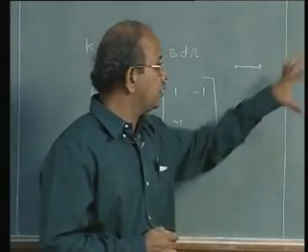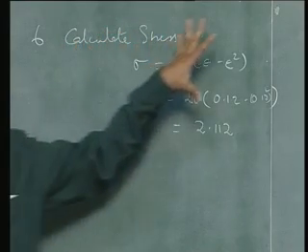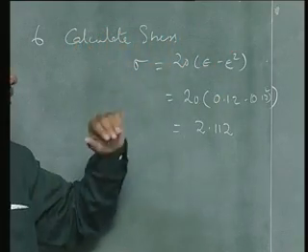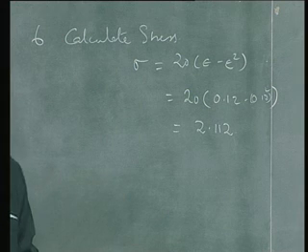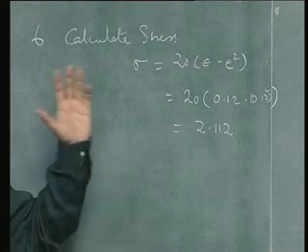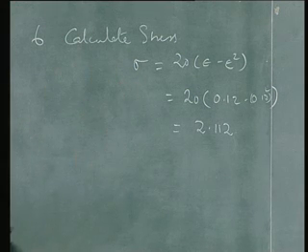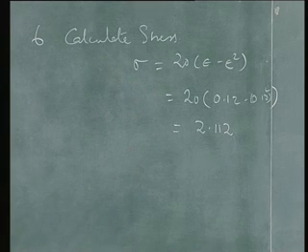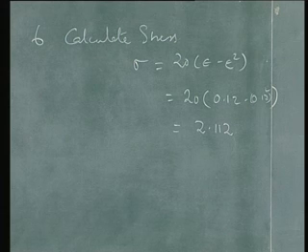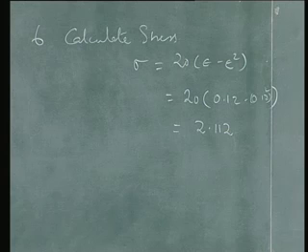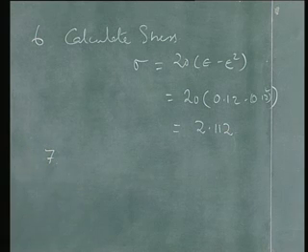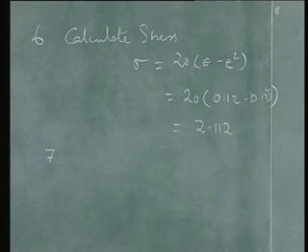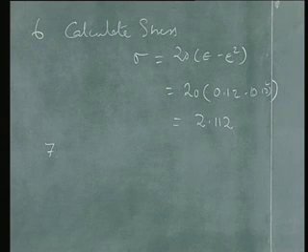So this step is usually called the stress update algorithm. This is a step which is very important. A lot of research has gone in to develop various algorithms for the elasto-plastic case. Is that clear?